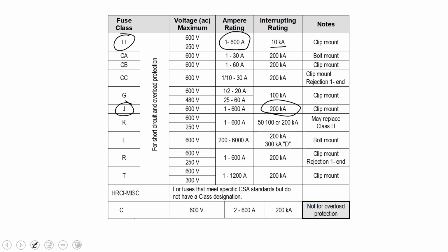Depending on the type of transformer you're using, or the network of transformers when they're put in parallel, you may have an extremely large fault current available. So we want to make sure that the interrupting capacity of our overcurrent devices is capable of interrupting the available fault current of our transformer. I hope that helped, and we'll see you on the next video.